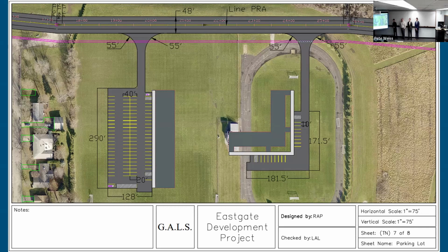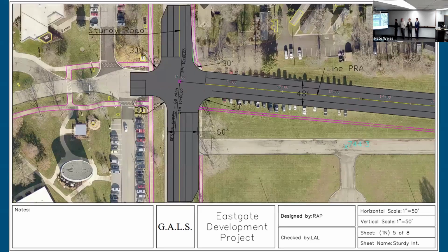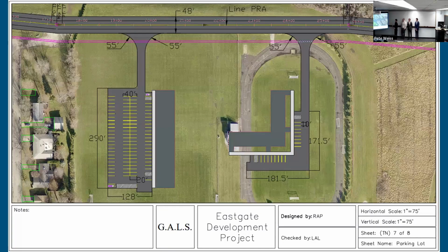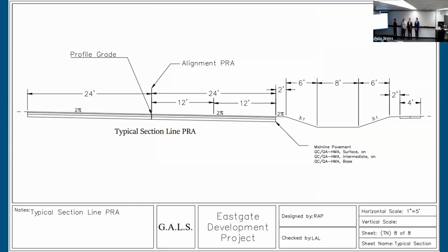While we're talking, did you go to your first section of the roadway that you showed? This one? There you go. 2% all one direction, all the way to the ditch. You're draining everything. It's sort of like super elevated. Yes. The reason is there wasn't really enough space over on this end. We wanted to do 2 ditches, one on either end, but when we looked at it, there just wasn't enough space to implement another ditch on the northern side of the road. So we went with 1 ditch on the southern portion and made sure everything ran down that way.